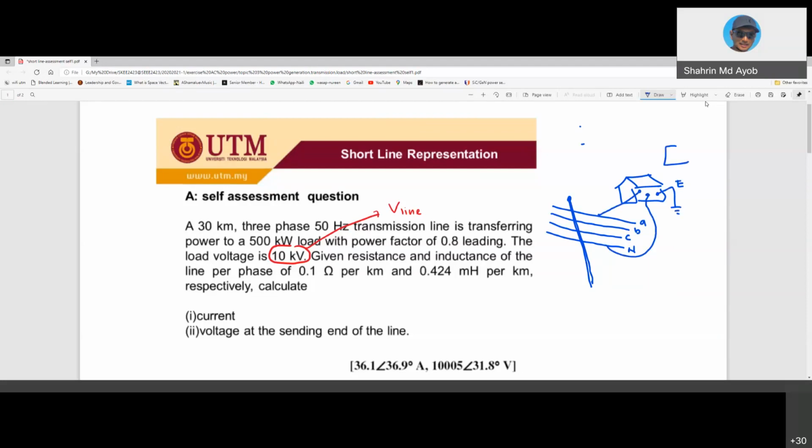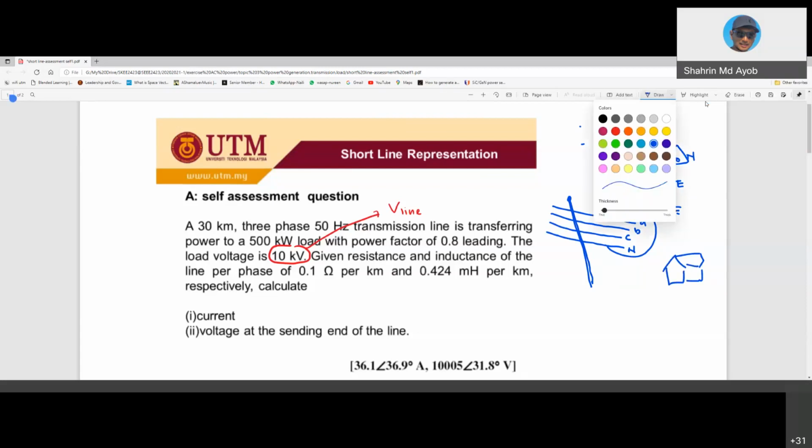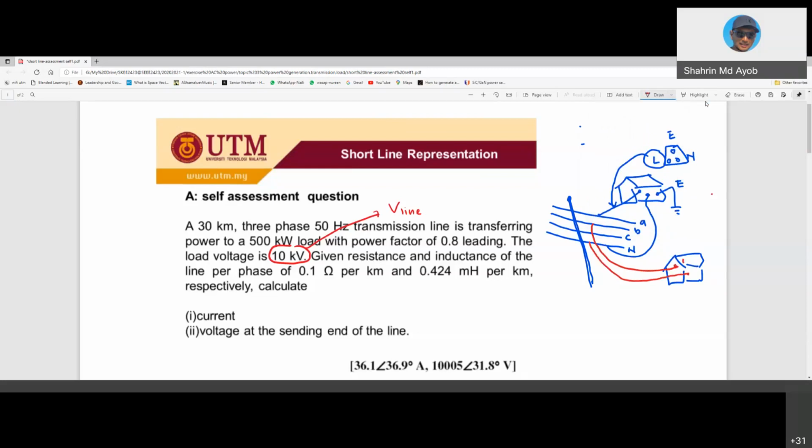So that's why you have three pins, which are earth, live, and neutral. This live is referring to either phase A, phase B, or phase C. Maybe another house uses phase B and the neutral point here, and the other point is earth.